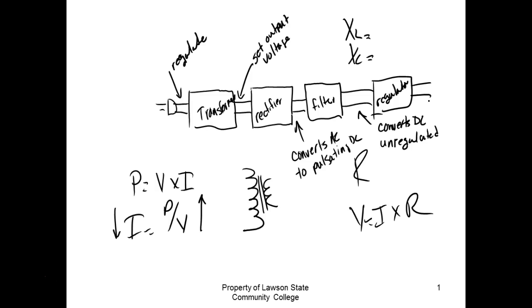So if I plugged it into 300 volts, it's not going to regulate. It's going to be out of its range, right? Or if I get 90 volts in, it's not going to regulate because I'm out of its spec, right? And this gives me a maximum current of 1.8 amps. I'm sorry, that's input. This guy is 2.5 amps on the output because it says 20 volts, right? Everybody understand that? So this is the setup of what we call a linear power supply.